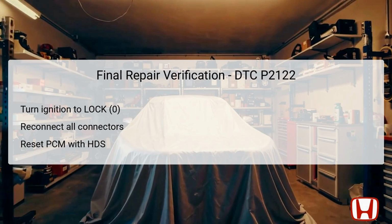Conduct the PCM idle learn procedure to enable the system to adapt to any changes made during the troubleshooting and repair processes. Finally, check for any pending or confirmed DTCs with the HDS to ascertain if the P2122 DTC reappears. If the code persists, this may indicate deeper issues that necessitate re-evaluating previous diagnostic steps and findings.